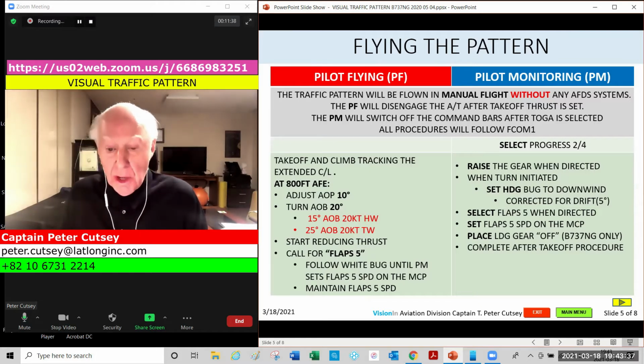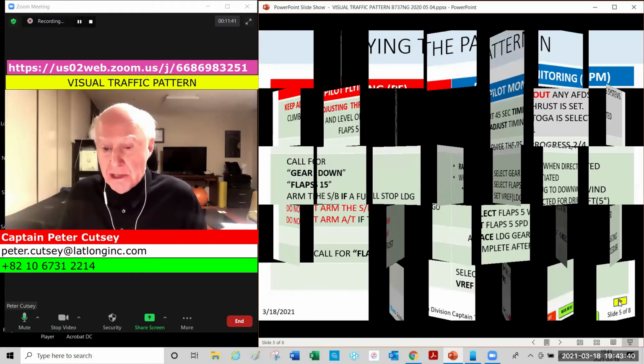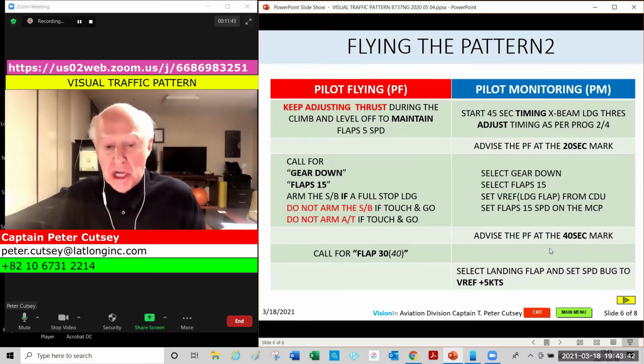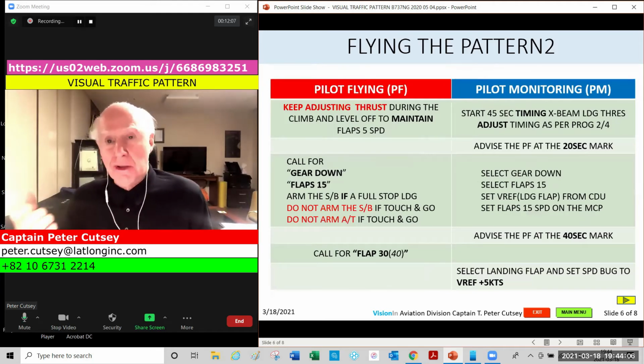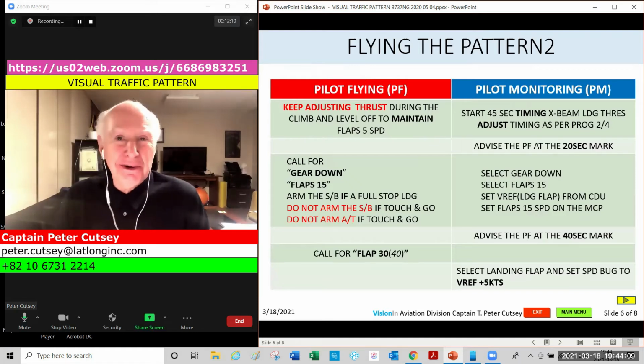Okay, so a busy time as both of you are helping each other. And remember, trim, trim, trim. If you put the center of the airplane symbol just sitting on the 5-degree pitch reference on the PFD, that'll be 6 degrees of pitch. That's a good reference point to start for 60 tons and approximately 58 to 60% N1. And trim, trim, trim, so that you basically are flying the airplane properly. And that's the whole idea of this exercise.